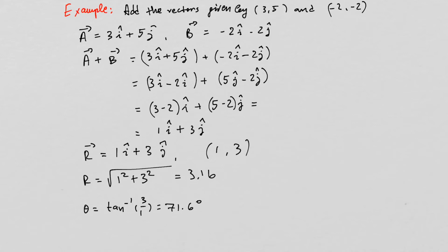So from here you can see that unit vector representation is extremely convenient to be able to do vector addition and also then determine the magnitude of the resultant vector and the orientation in space without actually having to do any graphical addition or representation of the vectors. You can simply work with the numbers as basic equations, and just performing simple algebra will give you the results.